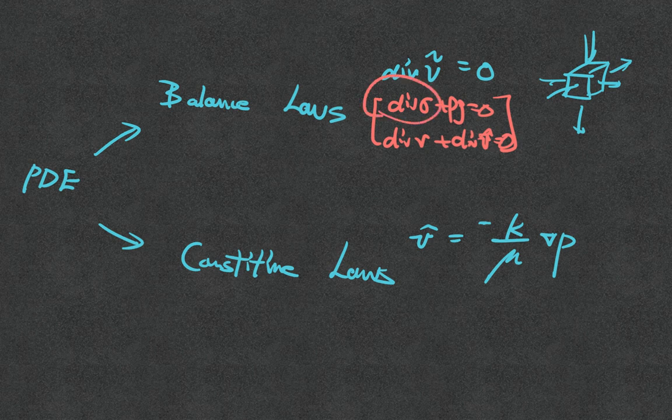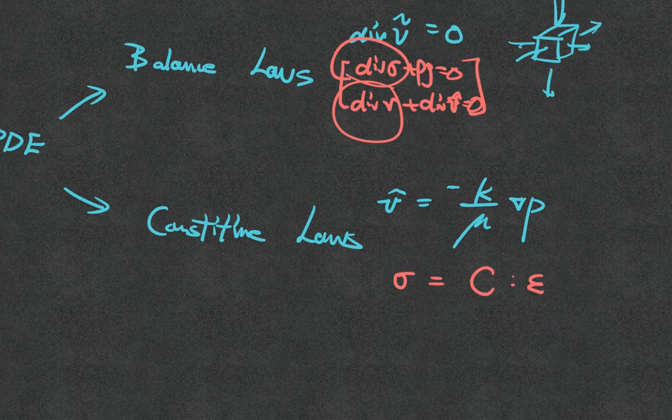Because of this term, I need to introduce an additional constitutive law, which is sigma equals C double dot epsilon, the linear elasticity, and I also need to introduce another law, the total stress equal to this minus pi. This is the second case, generalizing from the solid part being rigid to adding the deformable solid. So what are we doing next?